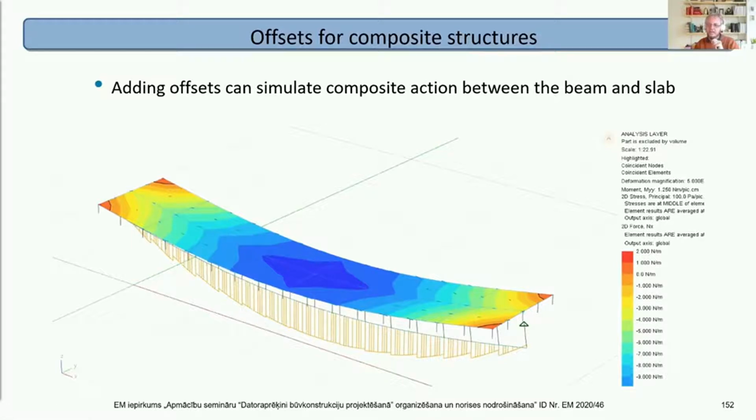Watch out for slab continuity. It's very difficult to model a full floor plate with everything working compactly and avoiding tension in the slab. You need to have, you know, non-linear orthotropic materials and goodness else.